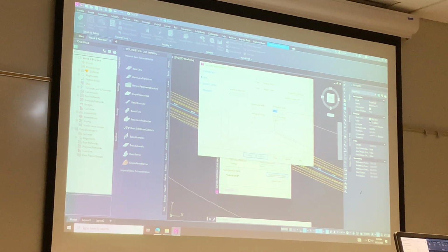All right, so we've got two lanes in each direction, two 12-foot lanes in each direction. Shoulders. We changed this to the outside, the right shoulder width. And we can see that it changes both the inside median shoulders and the outside shoulders. But we care about the outside.